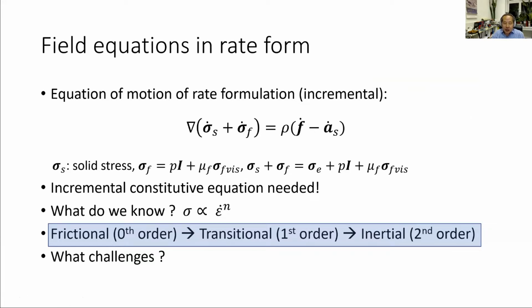If you look at this equation, the solution is also very familiar. You could basically use the same tools I just showed you before. But what differs from the approach before is that, because of this rate, you will certainly need the constitutive equation for the incremental form, for the stress rates. So that's the difference. Now I just want to have a look at two aspects of the whole thing.